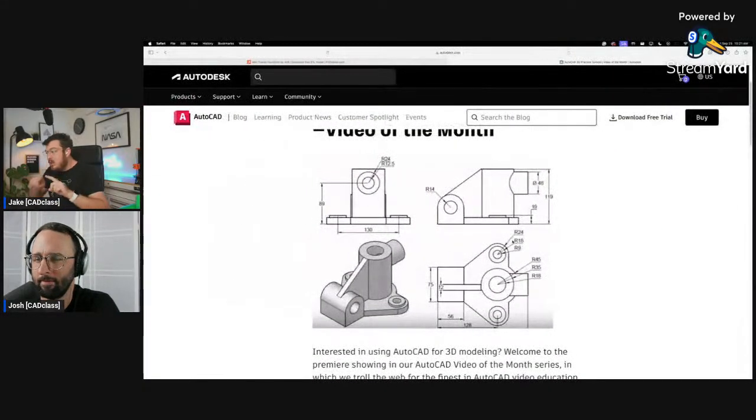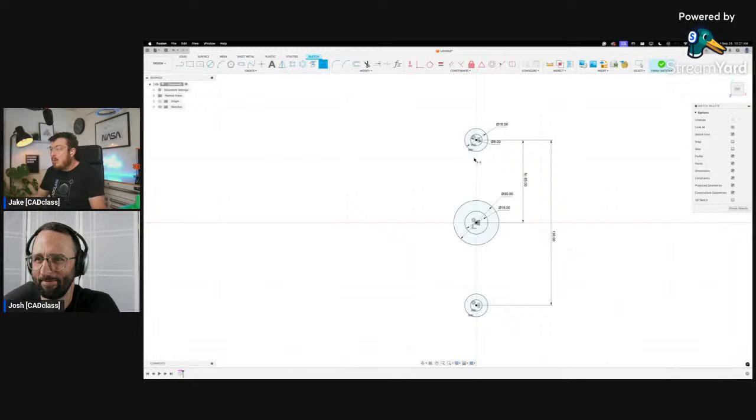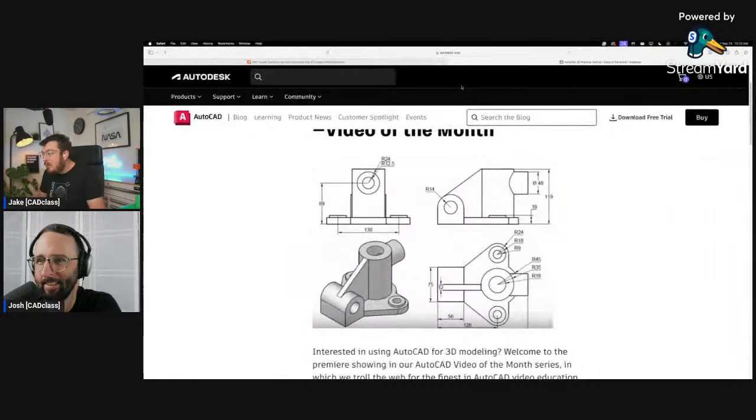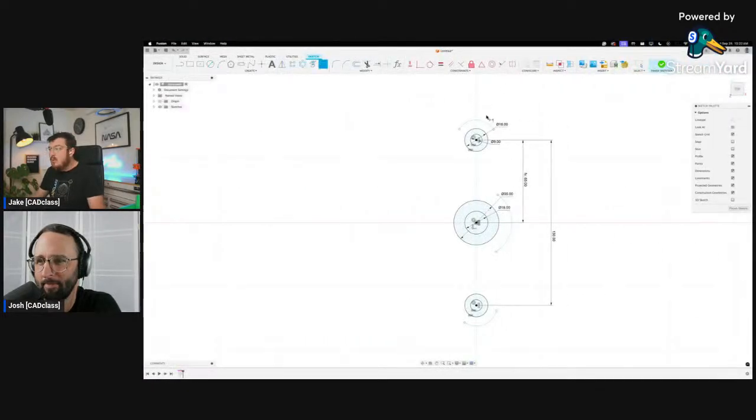Then that's going to be an offset curve around there going into it, back down. Okay, so that's going to be a series of arcs. So I'm going to be going into the create menu and making a center point arc. So there's going to be an angled line from there that goes around. Similar thing on this point, center point arc, and then mirrored on that side as well. Okay. So then I want to say that the outer top is 24.